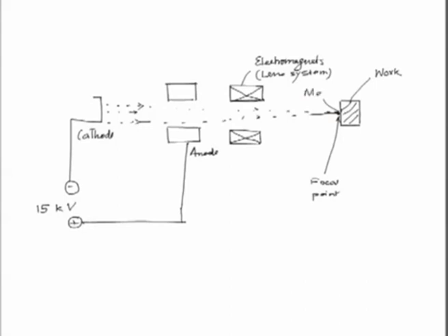So, the melting of the material will take place locally on this portion, and then with subsequent heating by the electron beam on the same workpiece, this material will come out as evaporated material, and the ultimate result will be that we get a cut or a machined portion on this work material. So, this we call the machined material.